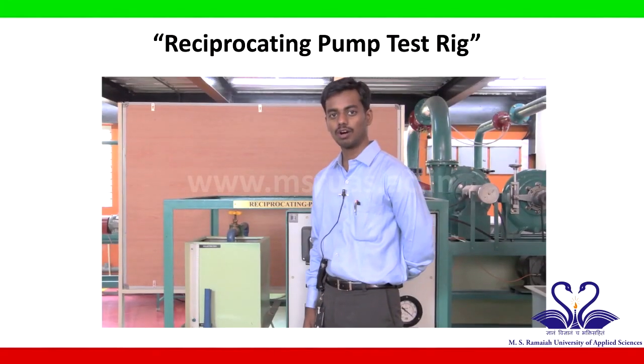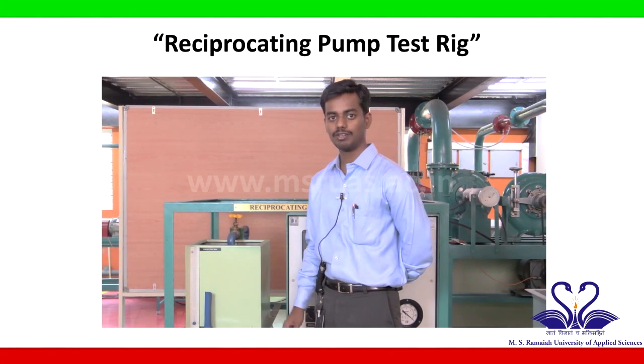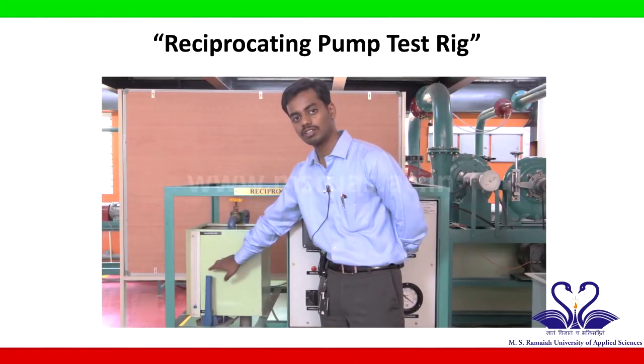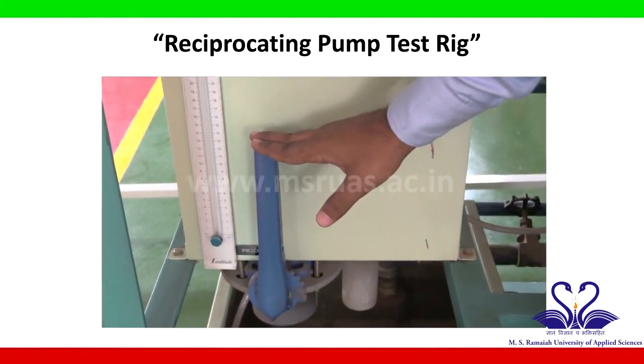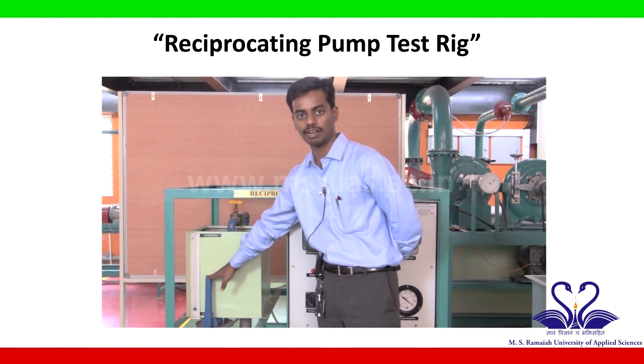The discharge of the water flowing in the circuit can be calculated using the collecting tank. By closing the valve of the collecting tank, we can note down the time required for a certain amount of rise in the water level inside the collecting tank.